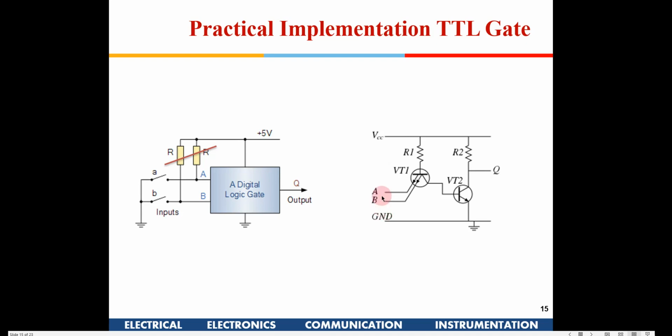In our simulation in LTspice, it doesn't cater for that kind of practical aspect. There, if you leave it open, it might be considered as 0. But if you are going to implement it on a breadboard or a PCB, then you will see that if you leave the input open, it is going to be taken as 1. That is only for TTL gates. For other families like CMOS, the things will be different. I am talking only about TTL gates.